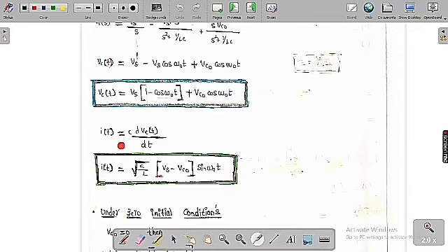So this is the current and voltage expression. Therefore, you know the value of Vc of t; just do the differentiation and multiply by C. Finally you are going to get I of t is equal to under root of C by L into Vs minus Vc naught sin omega naught t. So these are the two very important expressions.